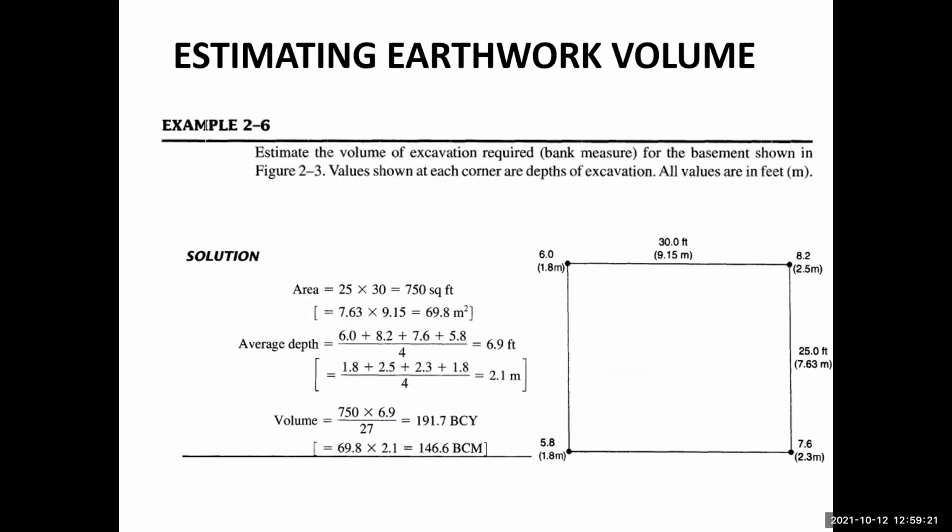So as a simple example, estimate the volume of the excavation required in bank measures for the basement shown in figure 2-3. Remember that now we are talking about excavation. In excavation, we will be dealing with the bank volume because we are dealing with the natural conditions of the soil. That's why it has been mentioned as bank measures. Values shown at each corner are depths of the excavation. All values are in feet or meters.